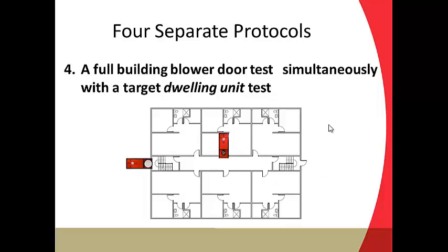So when we depressurize the entire building and bring this unit up to pressure, it's like a duct leakage outside test, for those of you who are familiar with doing that type of test. So this fan is cruising at zero pressure to the conditioned space. We're keeping this at the same pressure as the rest of the building during the test, and then there'll be no leakage to any of the adjoining spaces, and the air moving through this fan is only the leakage to the outside for that dwelling unit.